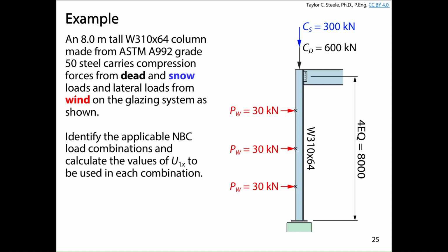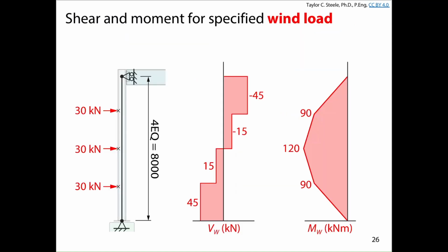Okay. I've gone ahead and already drawn the shear force and bending moment diagrams. This is not a lecture on drawing shear force and bending moment diagrams. What's important here is what the moment is. It's 120 kilonewton meters. And the shape of the moment diagram comes from a series of point loads acting along the length of the beam. Okay. So basically what we need to do is figure out what the factored forces are on the beam and